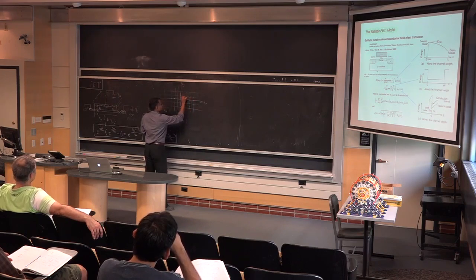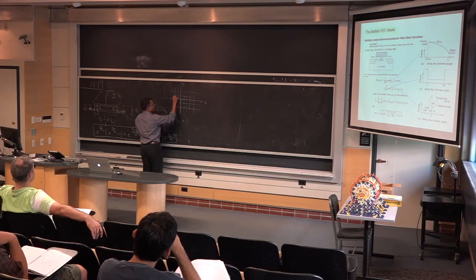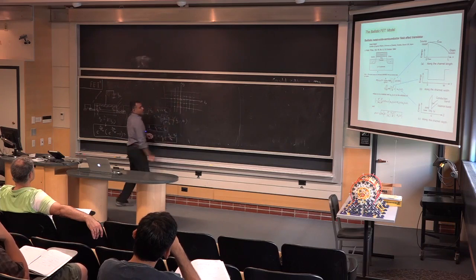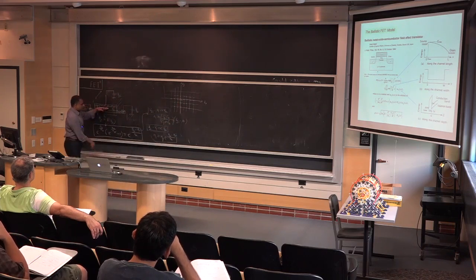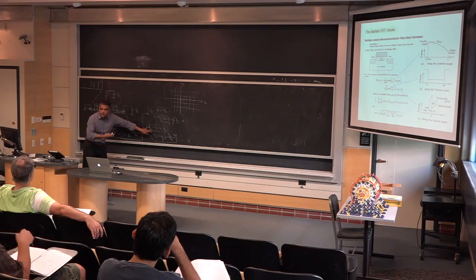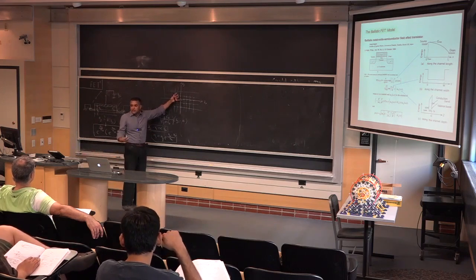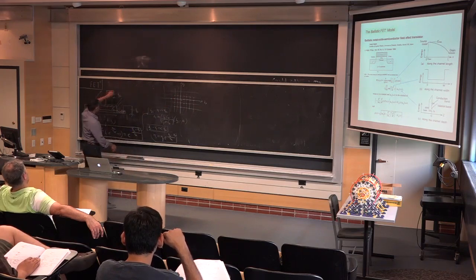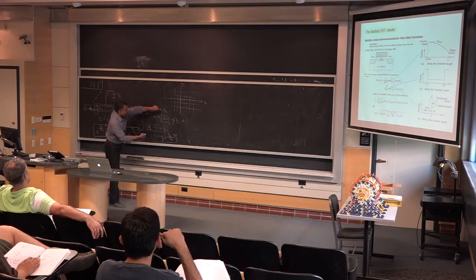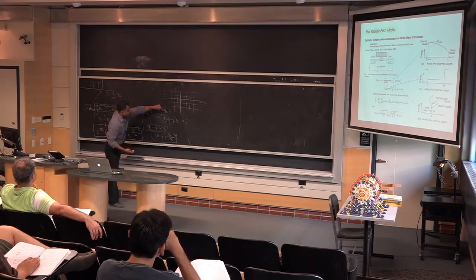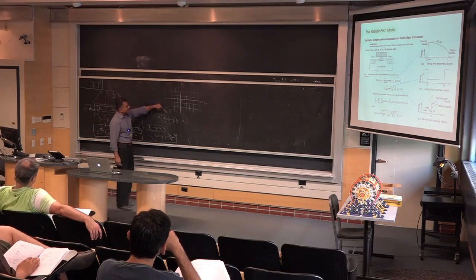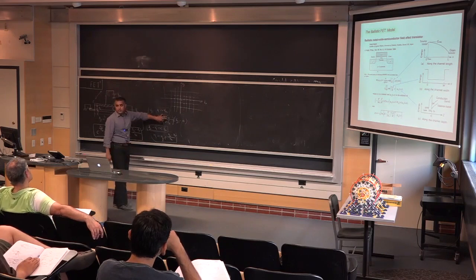If you had a very low density of carriers, let's say that's our origin, O, if you're sitting deep down in the off state, pretty much all modes are empty, very low occupation function. And then I crank up the gate voltage, take it quite a bit above threshold, a few kTs above threshold. And then you see you have quite a bit of carriers now, right?